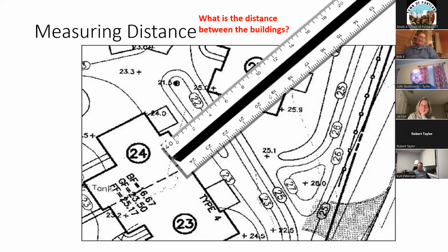No, so I see what you did there, but the reason that we have the different scales is that this recalibrates. So what you're looking at are not inches. This is not 1 inch, 2 inches, 3 inches, 4 inches. This is 40 scale. So the 0 to the 4 is actually your first inch. This is 40 feet. So at 40 scale, there's 10 feet, 20 feet, 30 feet, 40 feet, 50 feet, 60 feet.